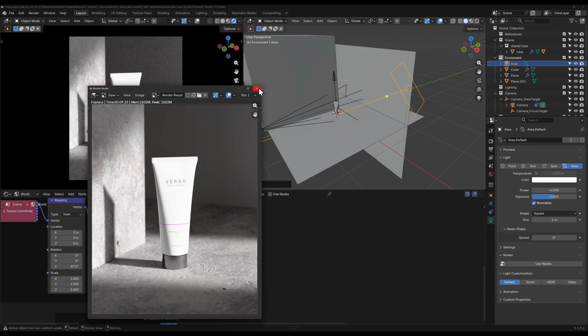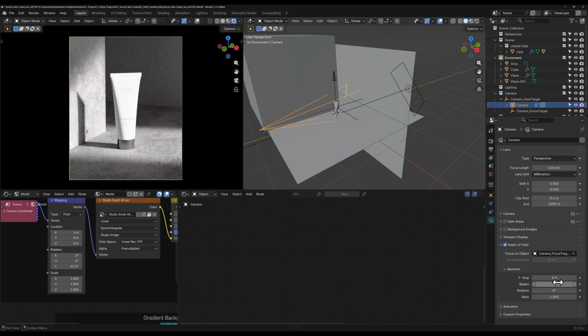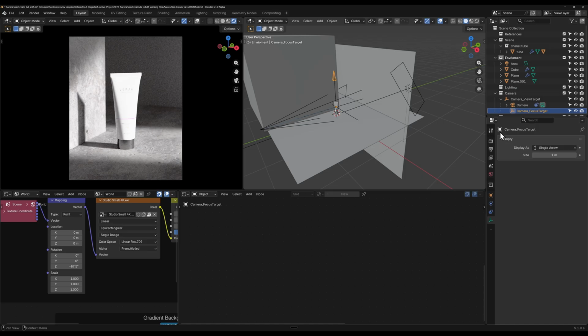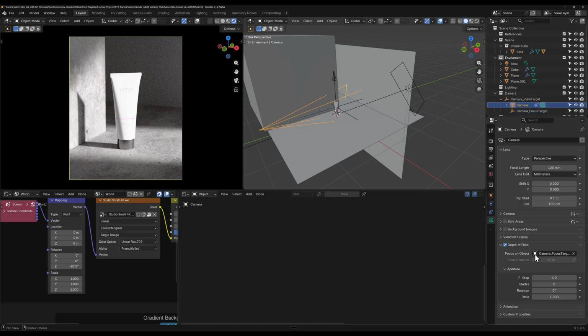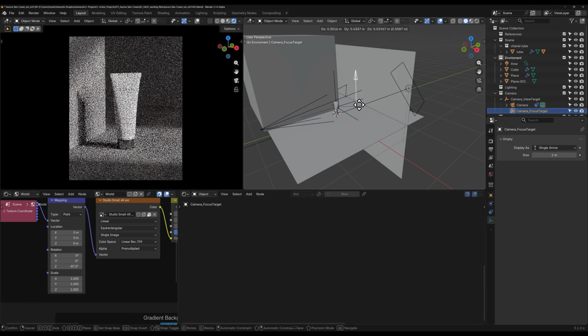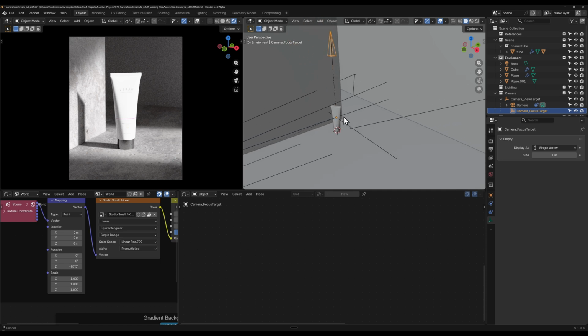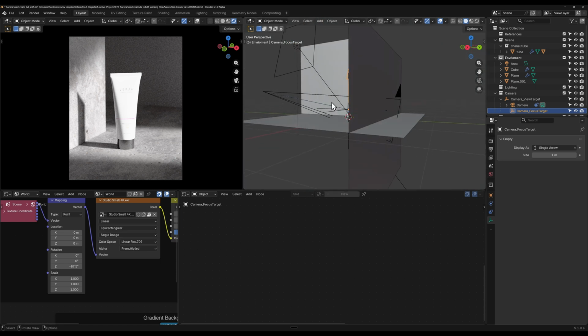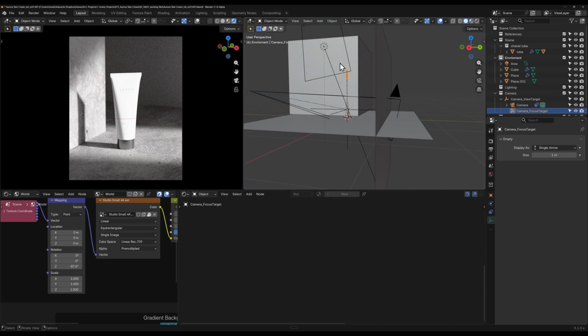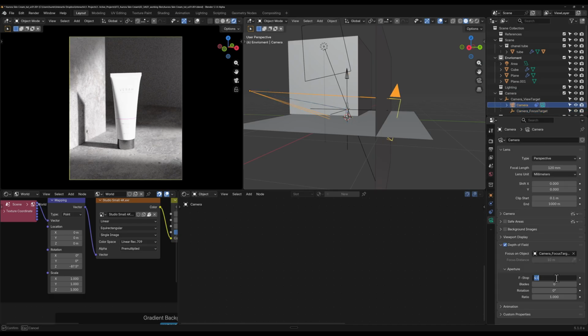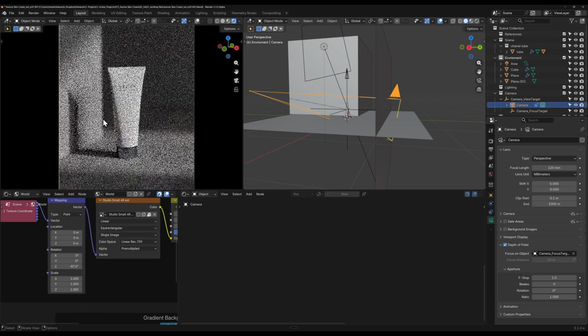We've got, actually the camera has also got an aperture, so it's got a focus target. So you can set the depth of field to an empty, and then you can move the depth of field around, which it's hard to see there, but basically what that does is it will only focus on a slim area, like between here and here, and the smaller that depth of field is, the finer the focus. So if I went 1, you can see how everything starts to go blurry.